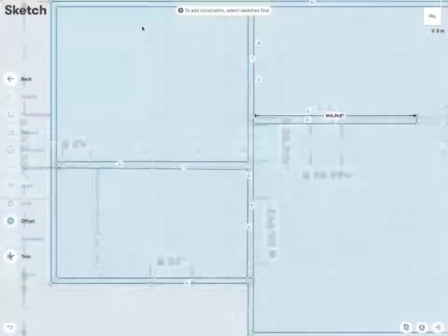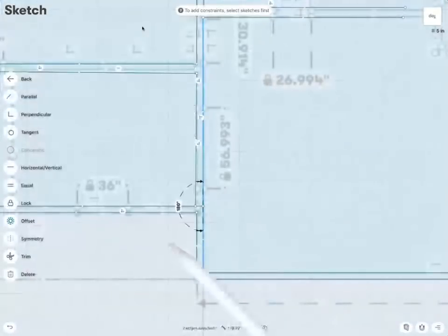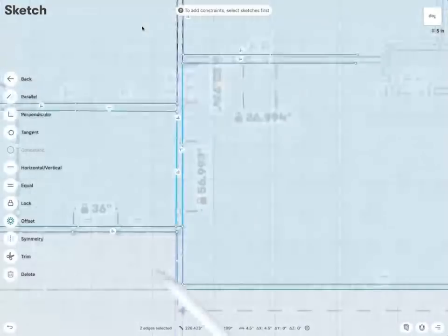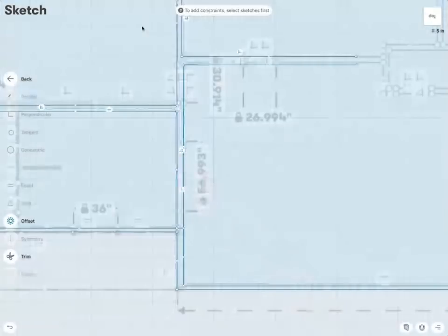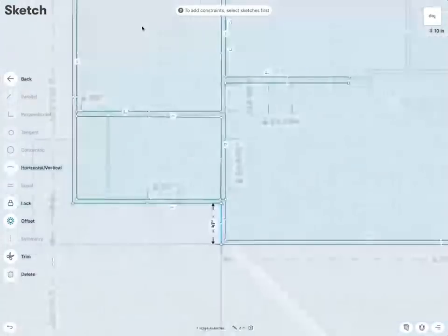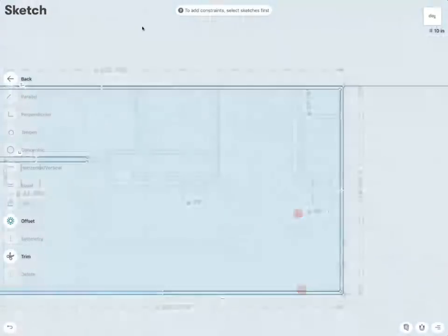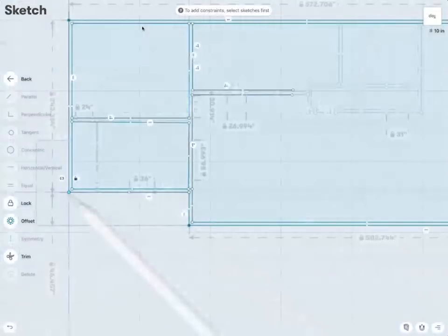So how do we deal with material thickness? This line is connected to this line. It should be flush, which is correct. And the distance between these two lines should be 4.5 inches. So I can do this via dimension, or I can also try to, hold on one second, something moved. So let's lock this line so this cannot move. I noticed that some of these horizontal vertical constraints moved. So I will update these constraints. And so that these edge points also don't move, I lock them. Very good.